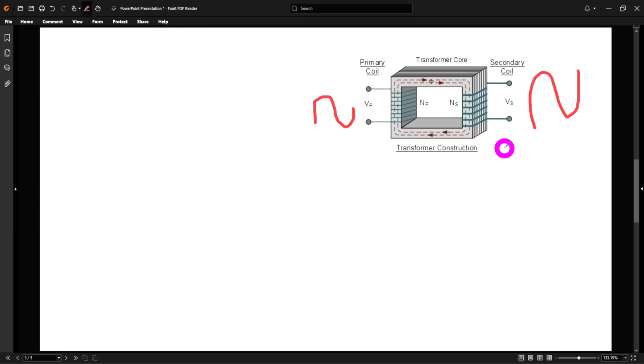Now this gives us voltage gain, and that sounds great, but of course this is a passive structure. It will not give you power gain. So as an amplifier, it's not really doing what we want it to do. For example, if I load the output of the secondary coil here with something that requires a lot of current, that actually translates to the input impedance of the primary changing because the transformers are coupled together.